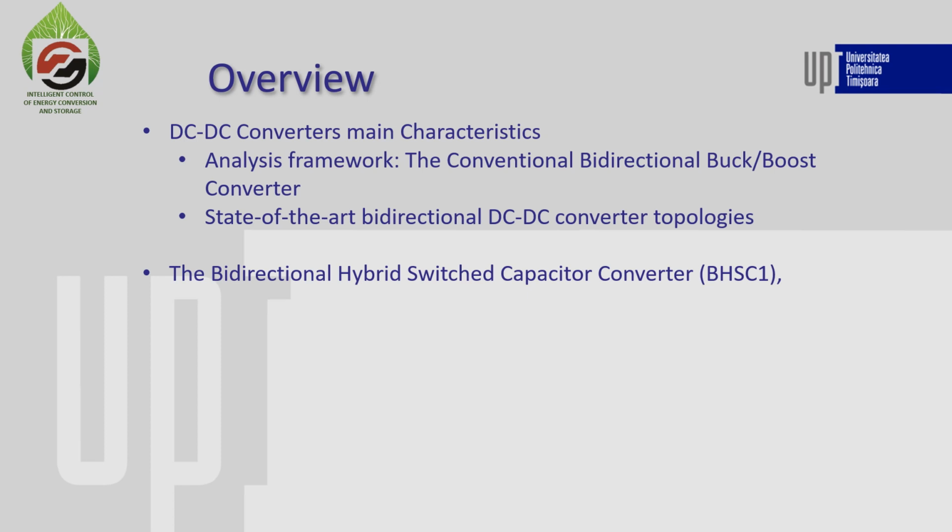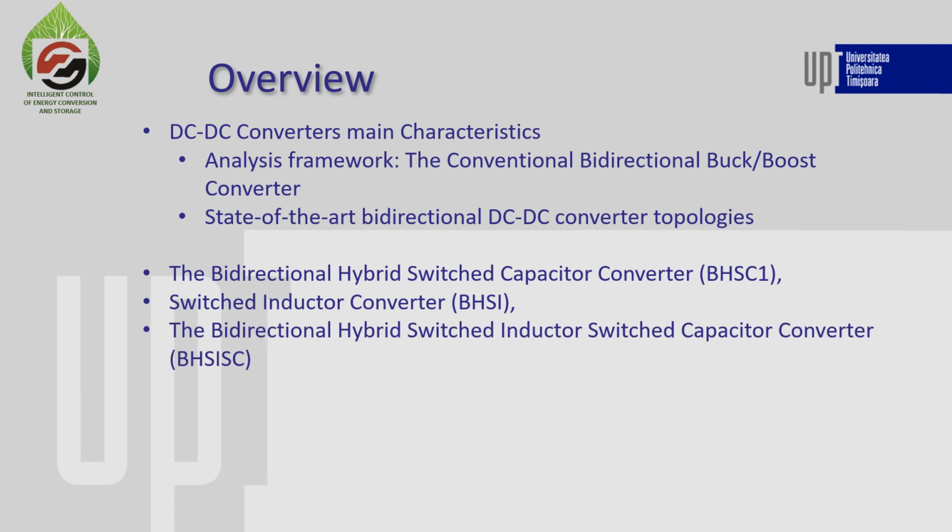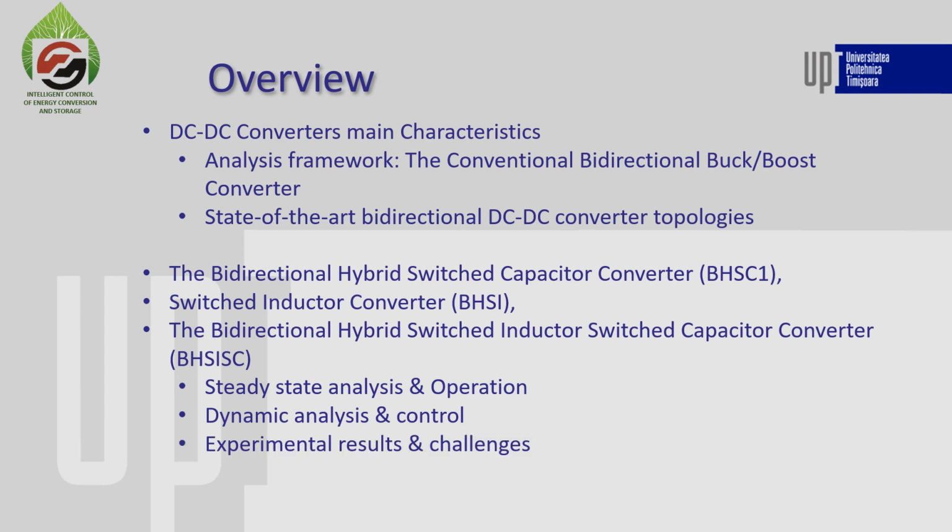I will then continue the presentation with three bidirectional hybrid DC-DC converters with a switched capacitor converter, a switched inductor converter, and a combined switched inductor switched capacitor converter. All three are analyzed in steady state and dynamic operations, and experimental results are shown. I will also discuss eventual challenges that appear in using these topologies. In the end, I will conclude the presentation with a comparison for all the presented topologies.